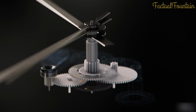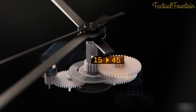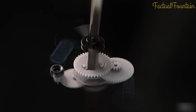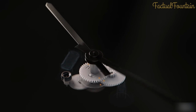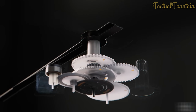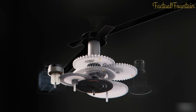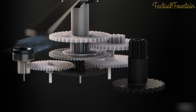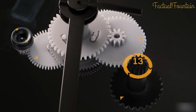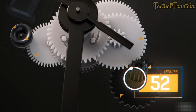And finally, the hour hand is driven via a 15 to 45 reduction to the idler and a 10 to 40 gear reduction to produce 1 rotation every 12 hours. As a result, we have 3 shafts rotating, to which the hands of the clock are mounted, each rotating at different speeds. The last gear is used to set the time, and interestingly, this gear has 13 teeth on it and rotates once every 69 minutes.